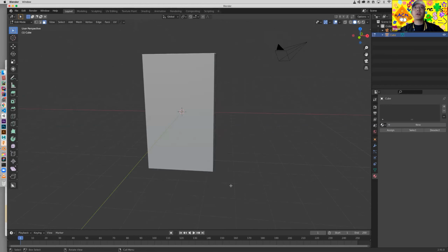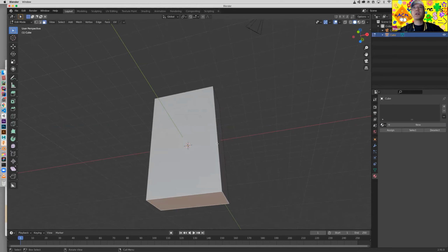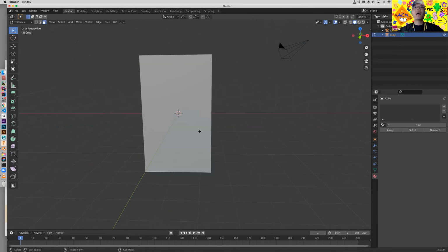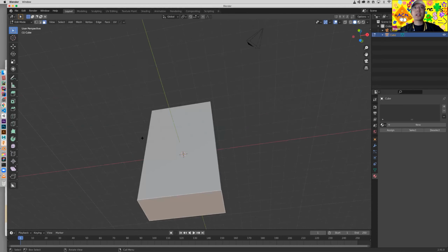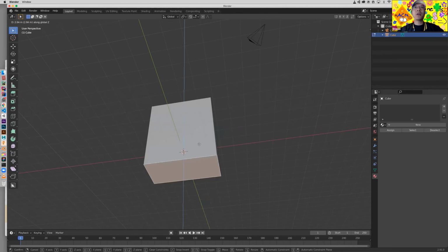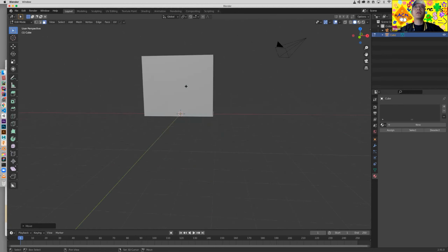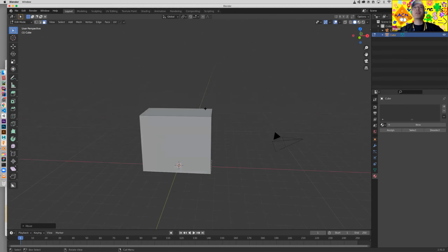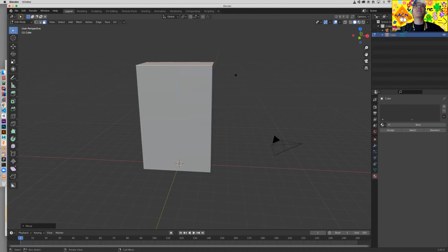So we're going to select the bottom plane and move it along the Z axis to basically get it near the 0 plane. So select it, face selection, and G Z to move it upward. Just a little bit up. Doesn't have to be really precise. Also G Z to move up the whole thing, the top face.